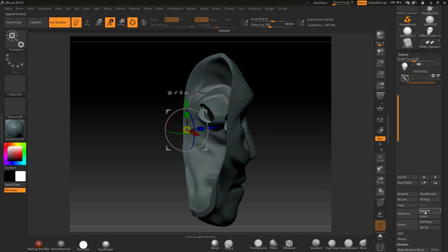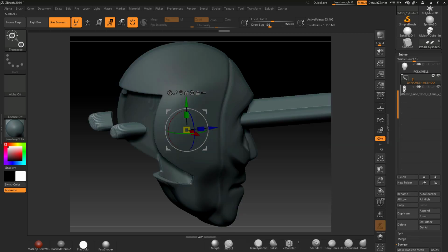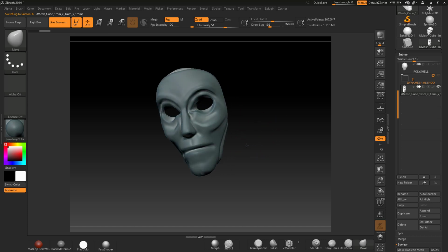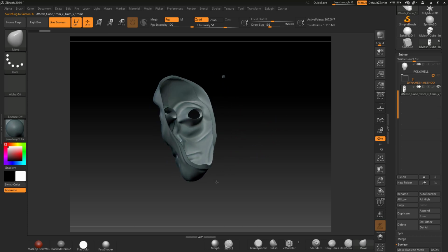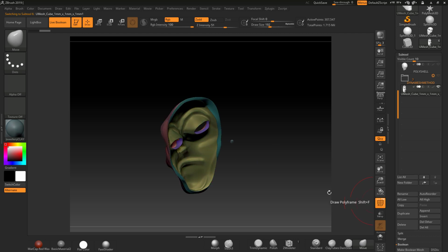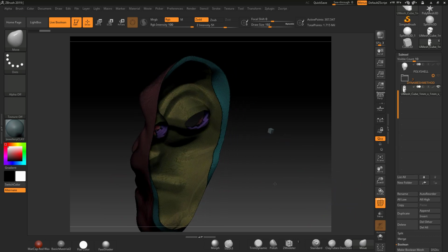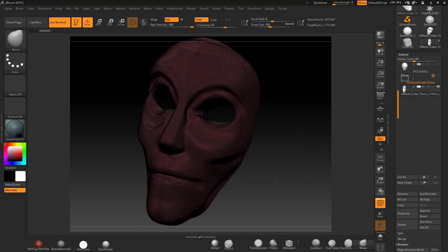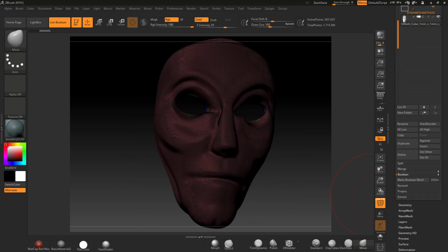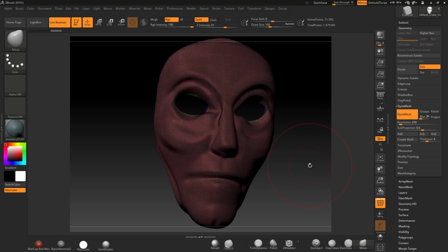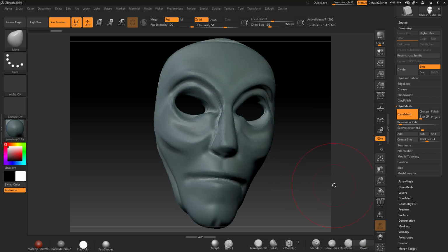Close them up, and I'll append in the new Umesh, which now has our 2mm gap. Obviously, go around the top. You're going to notice it's all kind of Dynamesh together, it's all Boolean together, so you might very much want to take this back into Dynamesh and clean it up, which is no problem. Set this on about 256, hit the Dynamesh button. I'm losing resolution there, so I probably want to set it a bit higher.